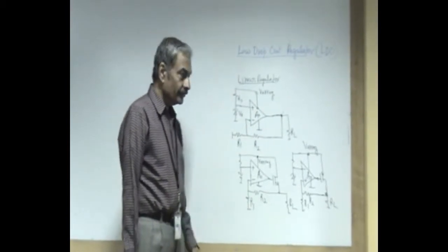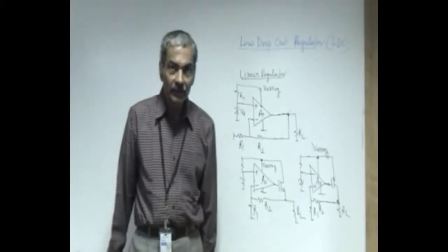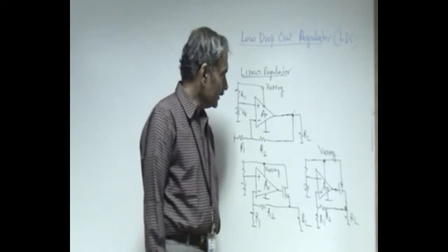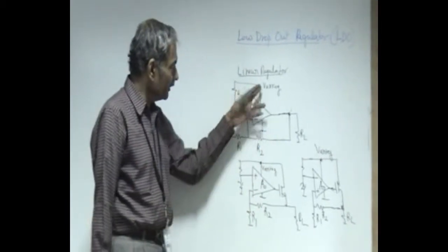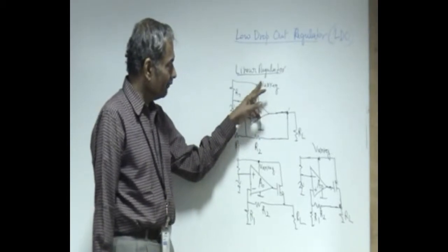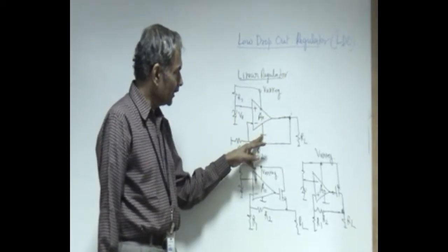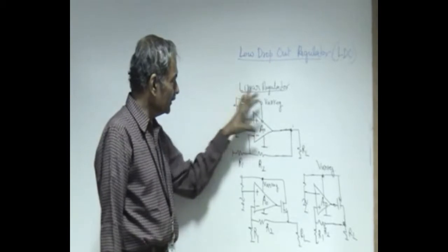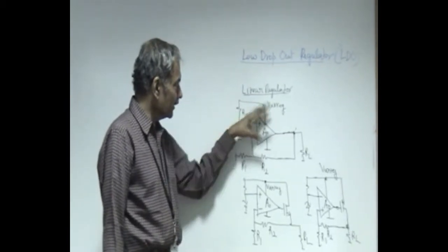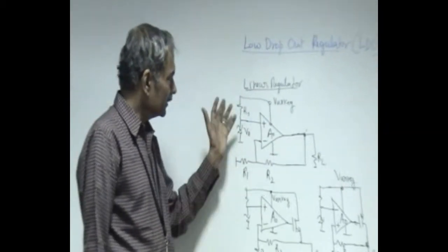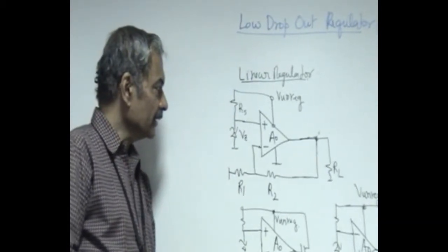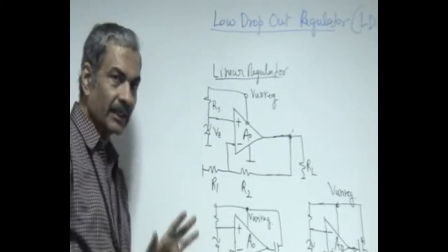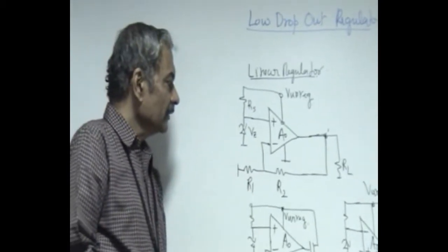A linear regulator is definitely a feedback principle of a non-inverting amplifier with one supply being unregulated, the other being ground. We are deriving the reference from the unregulated supply. Let us say there is a circuitry that makes it independent of supply, temperature, etc. So the Vz is a reference which is constant, right?